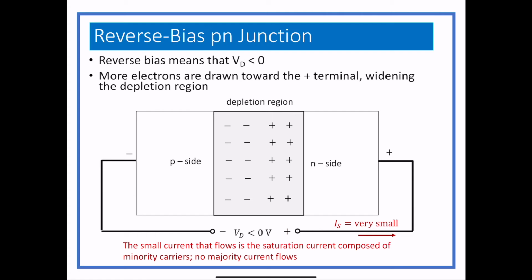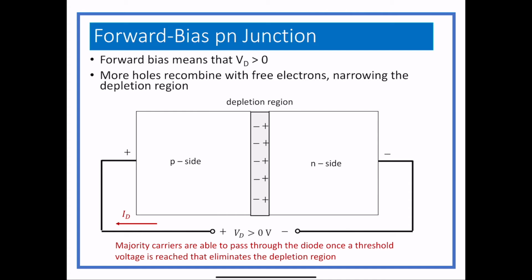So that's one way. That's a reverse bias. That's basically a DC voltage that's applied that makes the ability to pass charge for a diode even worse than what it was initially. The other way we can do it is a forward bias. In a forward bias, we apply a voltage that pushes the depletion region to be narrower. So we get a positive on the P side and a negative on the N side, and that causes the depletion region to shrink.